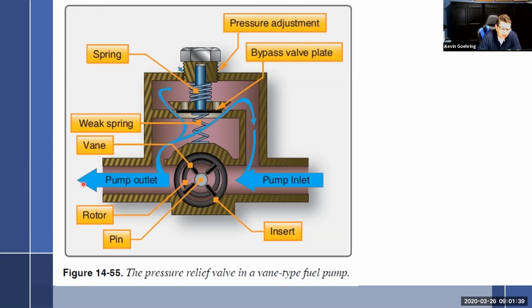But we have to think about a couple of things. Number one, I said that the centrifugal pump is used for starting the aircraft. And the centrifugal pump is also used as a backup. So that means we must have some way around it in case things don't work. Well, the way that works is if this pump is not running, like the engine's not running, so I run the boost pump, fuel's going to come this way, and I always got to think about how this goes here. It's not going to make it through anywhere here, so it's got to come up, and it's got to find its way down through here. And so that's what this spring is for here.